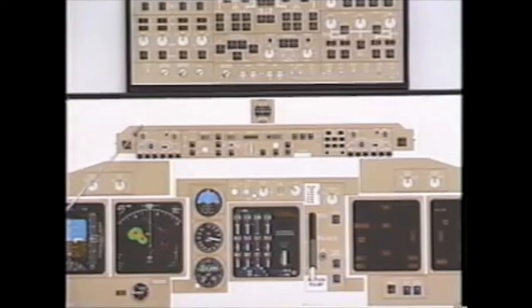Specifically on the EFIS control panel, we have a decision height and MDA option. Decision heights are radio altitudes, displayed in the lower right-hand corner of the attitude indicator. MDAs are MSL altitudes and are displayed in the upper right-hand corner of the attitude indicator. SOP is to select one or the other. Do not have both displayed.